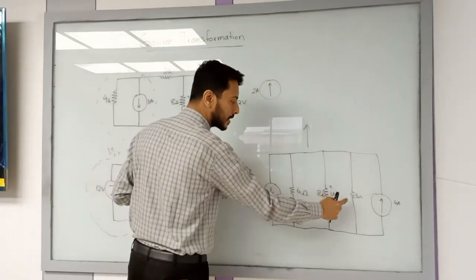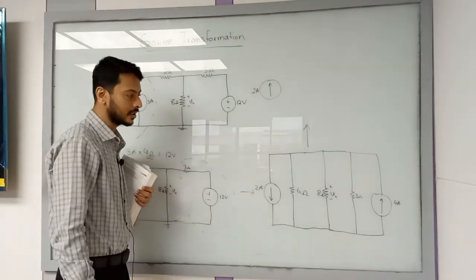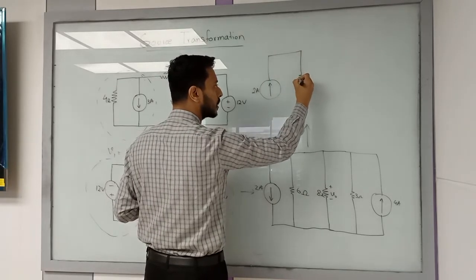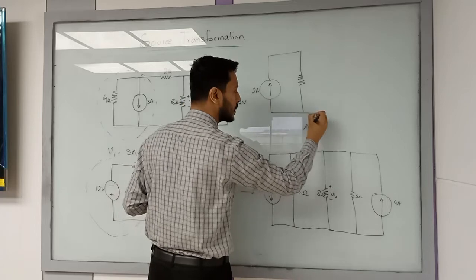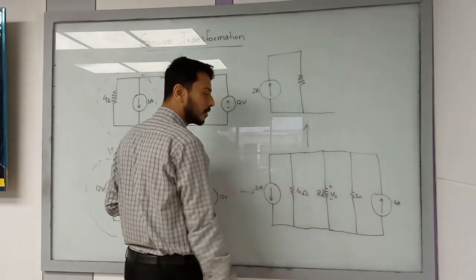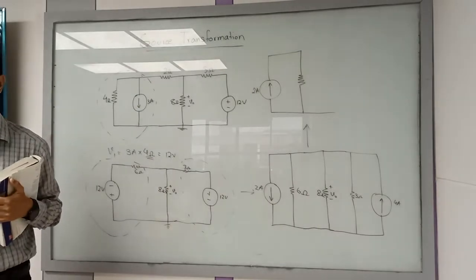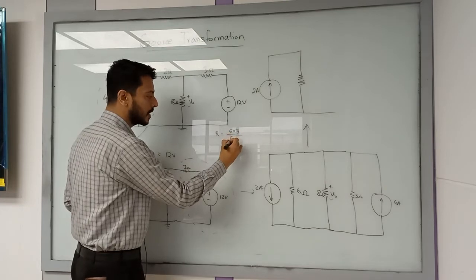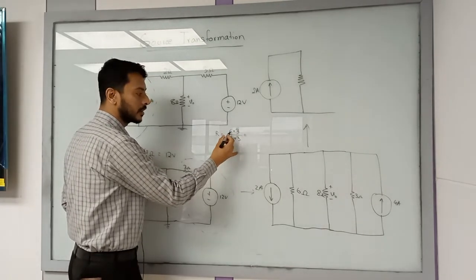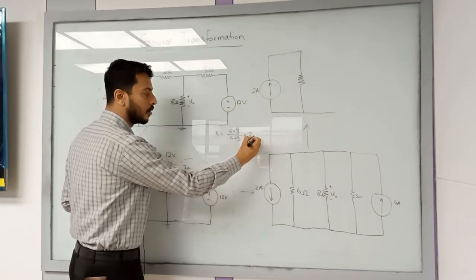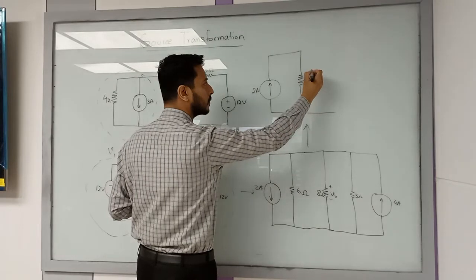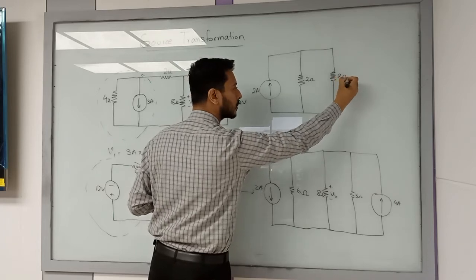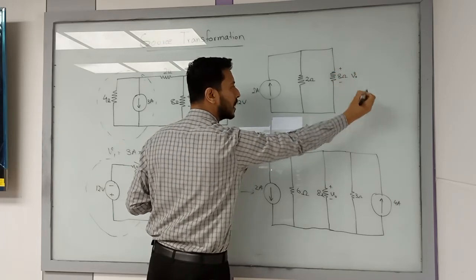And you have these two resistors in parallel, 6 and 3. If you calculate that, you can bring it to a single resistor. So what will be the value of the equivalent resistance of 6 ohm and 3 ohm? R should be equal to 6 into 3 divided by 6 plus 3. কত হয়? This is 2 ohm. So this will be 2 ohm. And you have an 8 ohm resistor present over here, with a voltage drop of V out, which we need to find.